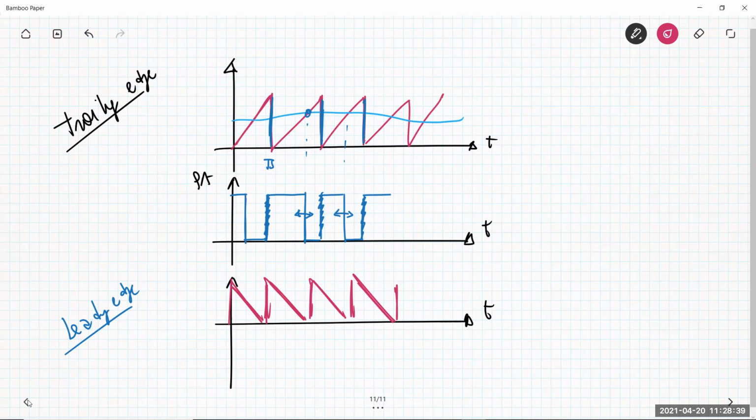Pulse frequency modulation can be employed, but again, there are a lot of problems, because the switching frequency changes, and this is not something that we can afford for our circuit. The filters that you have at the output for the modulation can be a little bit more complicated. Also, EMI filters can be more complicated for compatibility.